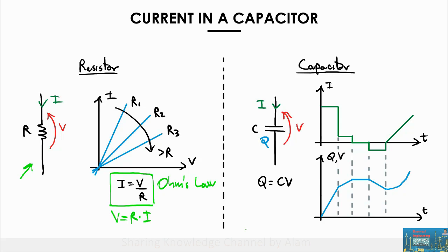Now, what we want to do now is to represent this relationship in a chart. This is a VI chart. The VI chart represents a VI curve, which is the voltage and current relationship of a component, in this case a resistor. So as you can see, a linear relationship is simply represented by a straight line. I wanted to highlight a few different things. So first of all, as clear from the equation, when the voltage is zero, the current will be zero. So all of these curves are passing from the origin of the graph. And that is always the case with the resistor.